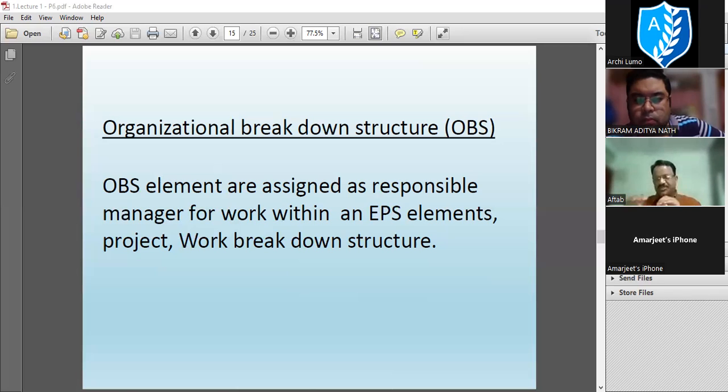Substructure means below plinth level. Basically it is below ground level, but normally we take it from plinth level. So below plinth level, everything is under substructure part, which includes foundation also, which is in contact with earth or soil. You understand me? This foundation part is in contact with soil.